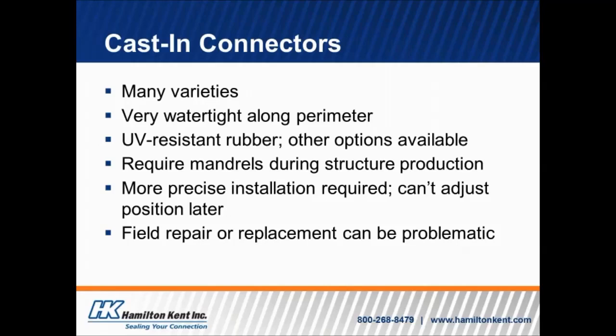Again, it's made out of UV resistant rubber, so that it can sit out in a precast yard or at the job site for a number of weeks and not have any type of deterioration. But there are other options available. Again, you can also get these manufactured out of a nitrile rubber in order to make it oil resistant.